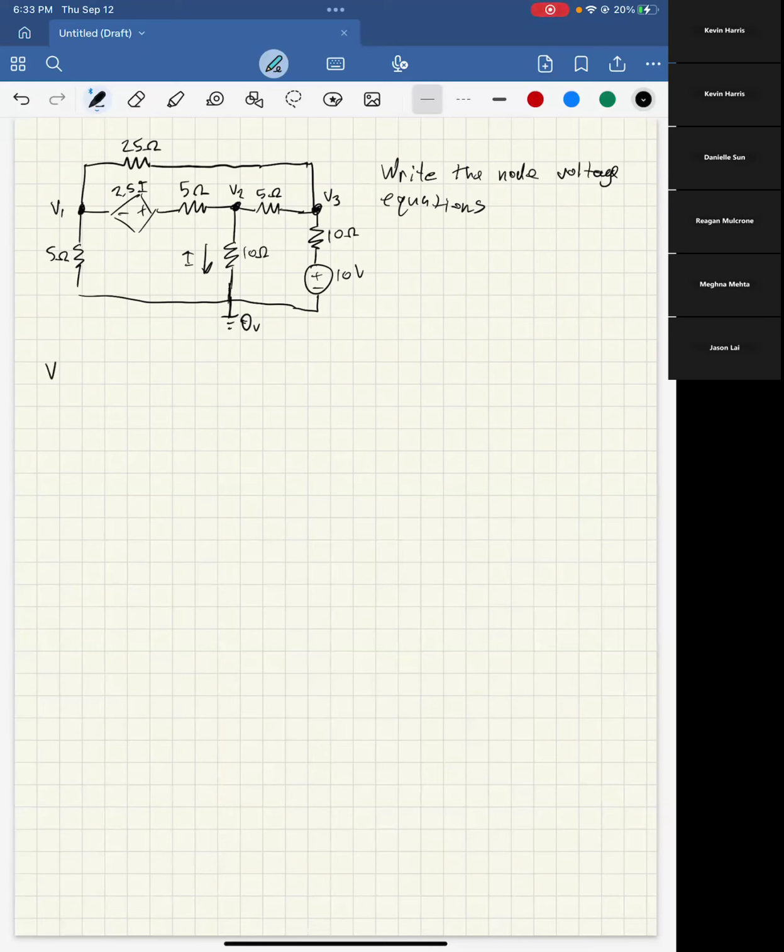So let's start with the V1 equation, straightforward. As I said earlier, I am going to be assuming that all currents are going out of every node, because that makes everything way easier. And if someone wants, at the end I could give a proof of why it doesn't matter what direction you pick. Basically, when you assume it's going the other way, you put a negative sign on the front, and then when you factor in that negative sign, it turns positive anyway, so it really doesn't matter. Anyway, I highly recommend you assume every current is going out unless you are explicitly told by a current source that it's going in.